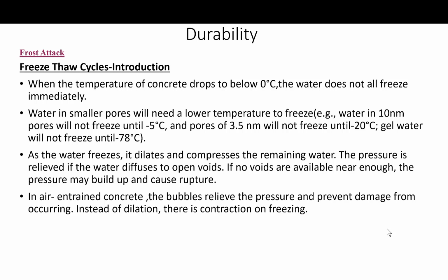It has been shown that in an unprotected paste, severe dilation accompanies the freezing, which leads to internal tensile stresses and cracking. In air-entrained paste, very little dilation occurs, and actually considerable shrinkage during freezing is observed at low temperatures. We will see why coming up.